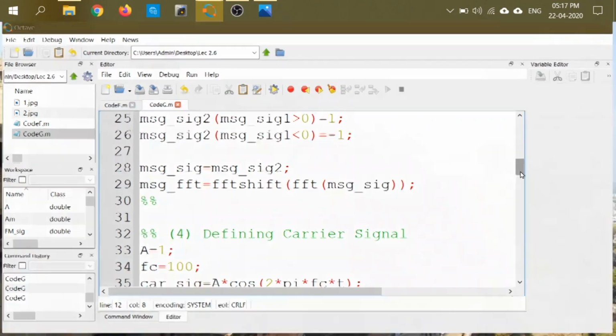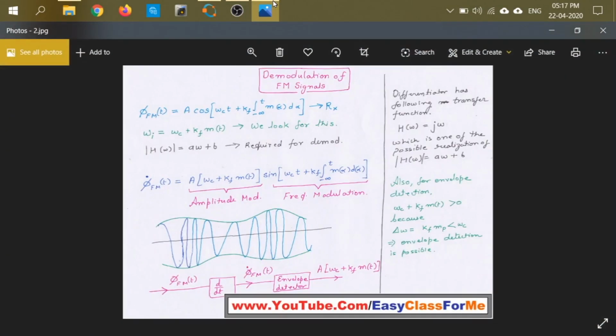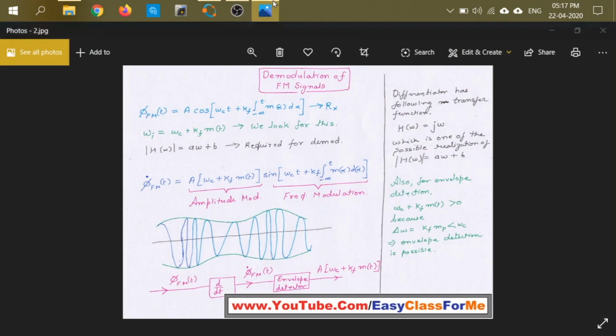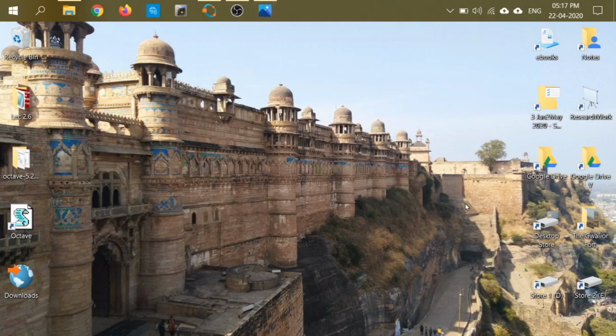So in this video we have learned a lot of things regarding this theory of demodulation and how to code this signal, and we will talk about other ways of demodulation of FM signal in the coming videos. And this complete theory is applicable to the demodulation of angle modulated waves in general. All you were interested in is the instantaneous frequency, and from instantaneous frequency, the phase can also be calculated. We already know this. And if phase and instantaneous frequency are available, both phase and frequency modulated signals can be demodulated. So this procedure is general and can be applied to any kind of angle modulated wave.